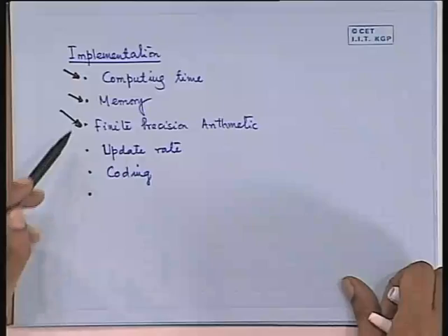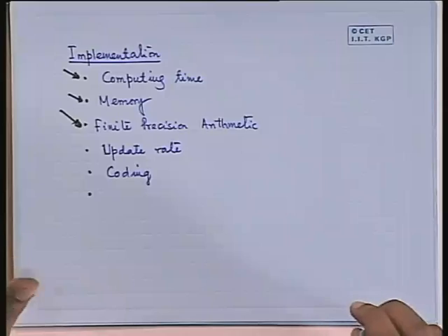Finite precision arithmetic. When you are coding your numbers, especially in rudimentary processors, using fixed point, not too high word length arithmetic, you need to be careful about the truncation errors. Things which go under what is called the numerical carpet. There could be a lot of dirt there and it could affect your results. Remember that, especially if you are going to use your results online for control, it's critically important. If somebody had my algorithm give a divide by 0 mid-flight, it is not pleasant at all.